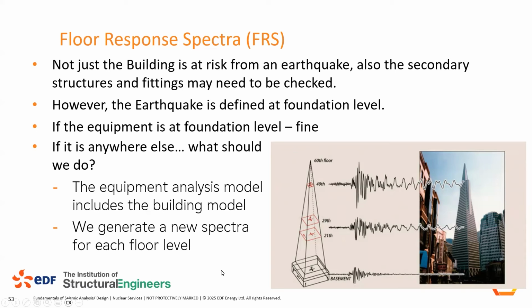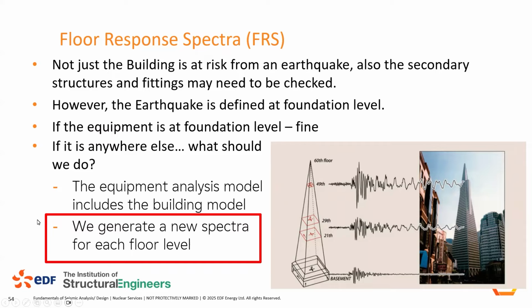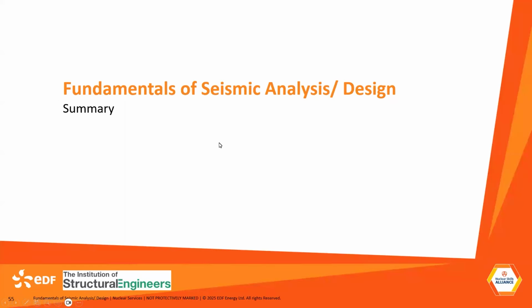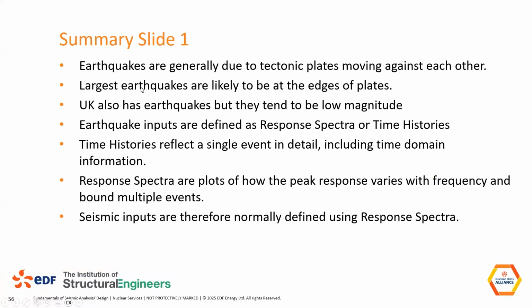So that's that. Generally, we would do the second option, where the structural designer will actually generate spectra inputs for each floor. So we would take our base input, extract values at the floor of interest, and give that to the equipment designer and say, okay, you're on the 21st floor. Here's the 21st floor spectra for you to use, and they can then consider their equipment in isolation. They don't need to consider the building. And that's it. Now, my summary.